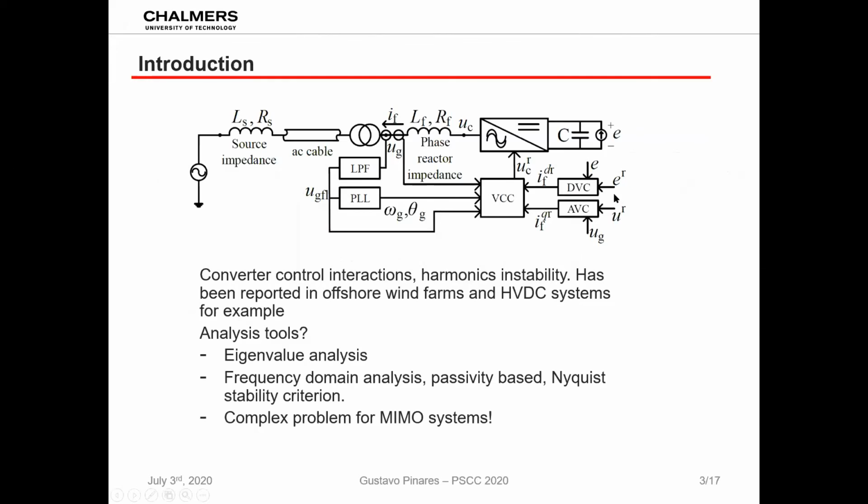Yes. So if we have the interconnection of multiple inverters and you suggested some new scheme that decouples the control, those new channels will be combinations of these inputs. And this means that to use your control, each inverter should take measurements not of the local, not of this current bus, but the measurements of its neighbors, right?